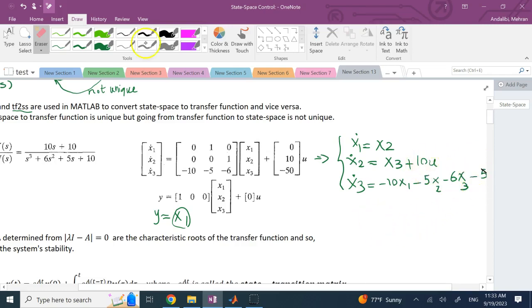Here, there we go. And if I know x2, does it mean I can also find x3? Yes. Look at x3. x3 is the derivative of x2. Of course, I also need to know the input signal, but the input signal is always a given signal. You know u already. What you need to sense is y. u is under your control. You can always measure it. So u is not an unknown.